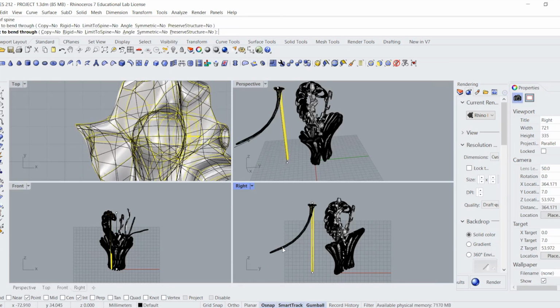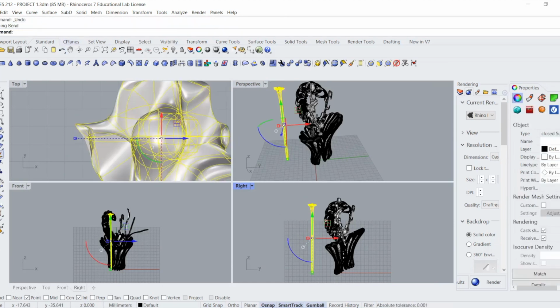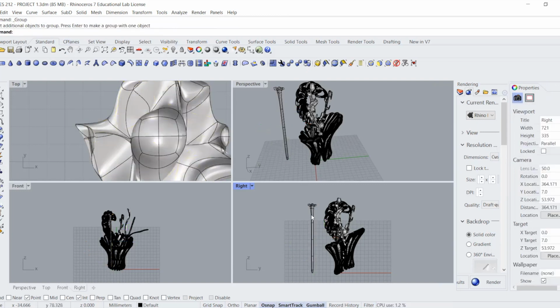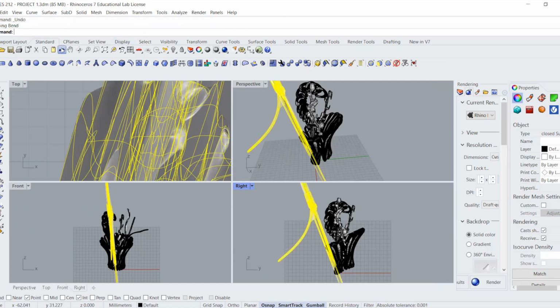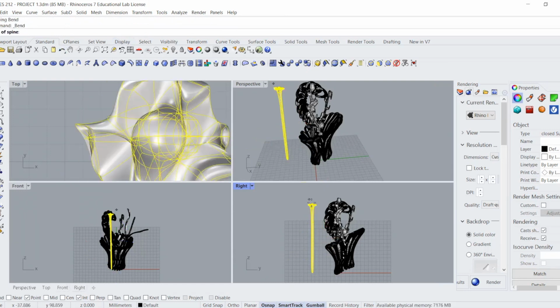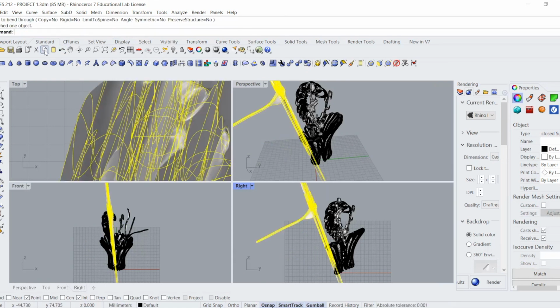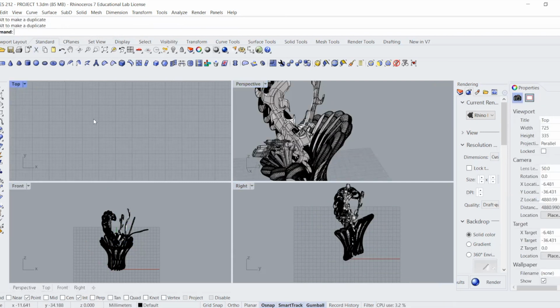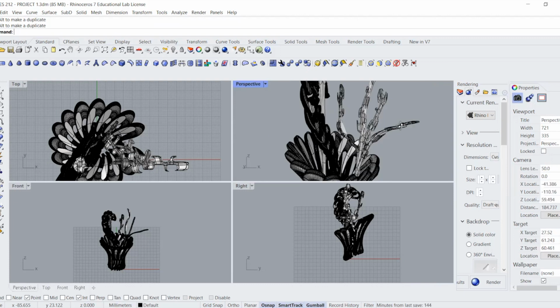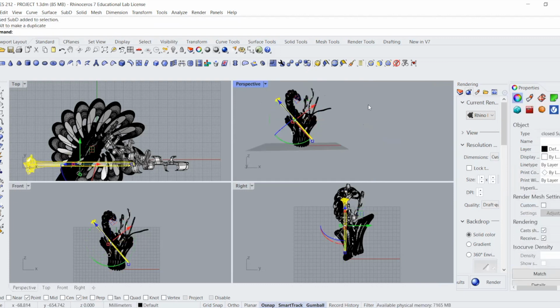While spending time on the flower for this SubD, it was very difficult as it kept stretching out the petal itself. Each time I tried to bend it, it kept repeating the same thing. So I decided to put it inside the tunnel, and then I put a flat surface and used the trim tool to trim out the excess surfaces that were coming out of the tunnel.